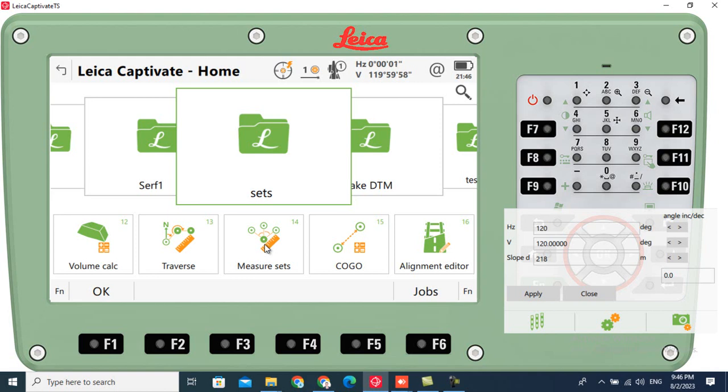So do I need to move to another point and measure them in a different way? No, I do this work on all the points of the network. If I have a network of points 1, 2, we did it on point 2, measuring 3, 5 and 6. So the next step would be to go to 3 and measure 2, 5 and 6 the same way. Exactly.